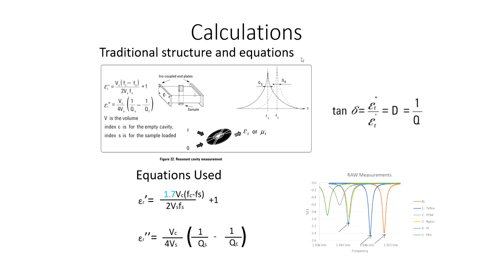In terms of the calculations, obviously it's lovely to get this data out, but if you want to do something with the data, you've got to look at the frequency shift, you've got to look at the change in Q, and you've got to look at other properties in order to get out the dielectric properties of the material.